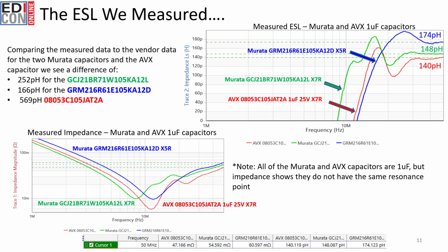That's simple, right? Look at that Grover equation that we showed previously. That inductance is mostly a function of the chip size. So we know what ballpark we need to be in, by considering that inductance is calculated on this Grover equation, which is the majority of the inductance of these capacitors.